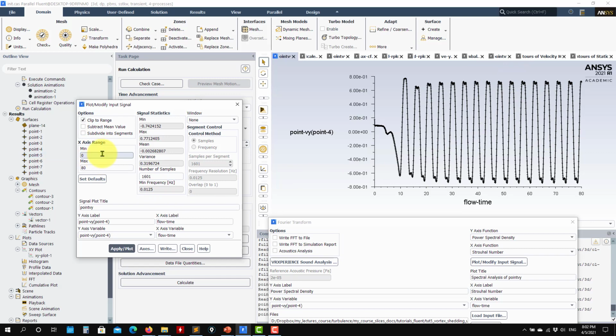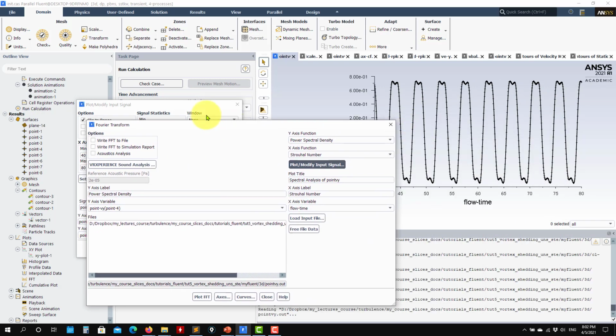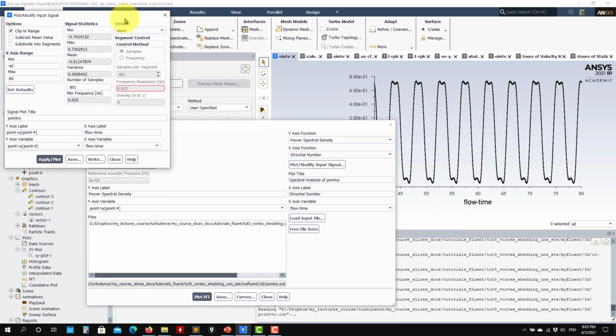Again, we have this, and from this signal, again, you can compute frequencies, okay, but also we can plot the power spectrum. And remember, that is the call to get the Kolmogorov law, the one that he predicted, the -5/3. But to do that one, you need to get turbulent kinetic energy, okay? So that is later, we're going to go into details.